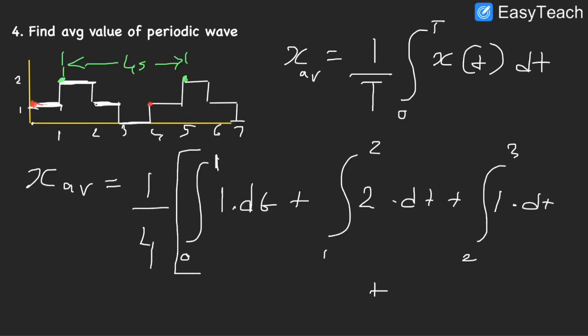That's another way to check. Most people make the mistake of considering this signal as having a time period of 3. But no, it's a signal having a time period of 4 seconds. That's why I showed you with reference to the point shown in green. So from 3 to 4 seconds, the value of your signal is just 0.